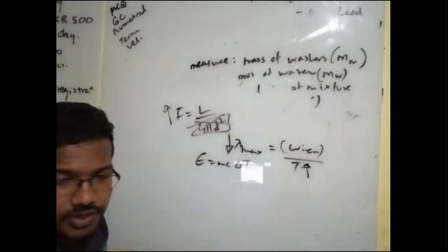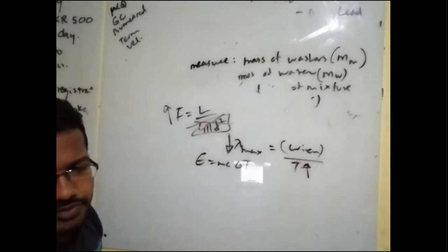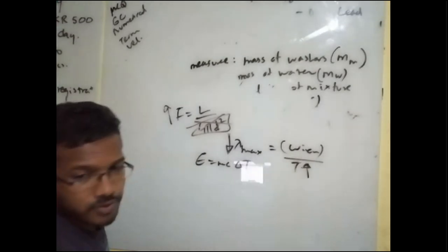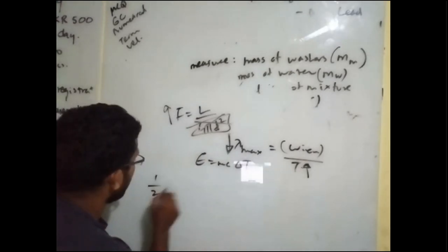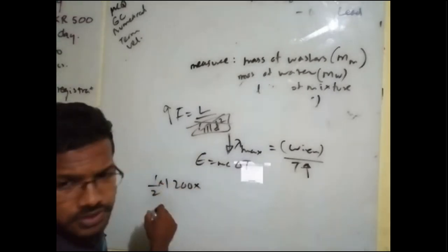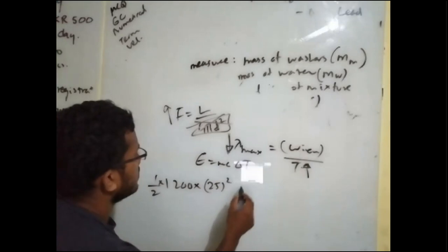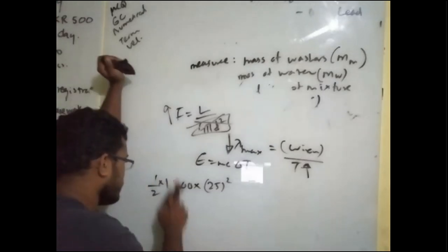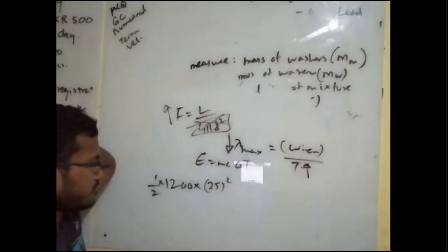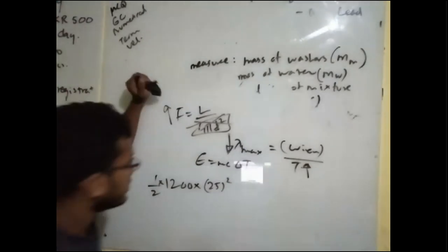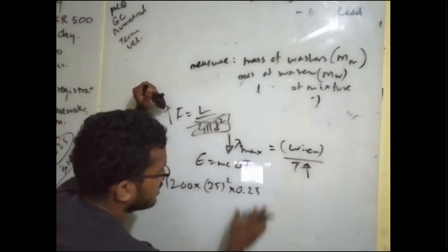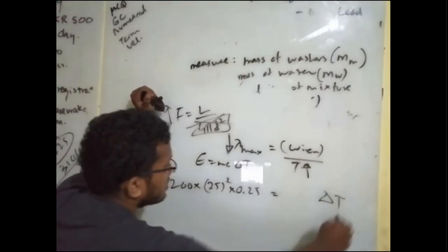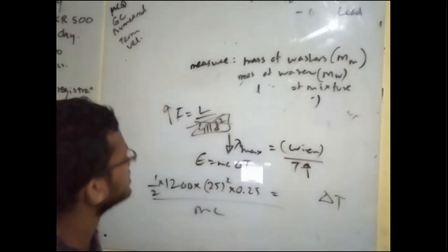I think they say a car of mass 1200 kg, traveling at speed 25 m/s minus 1. Oh, so the kinetic energy is converted to thermal energy. Read the question properly. Tell me a formula. Half mass velocity square. Am I done on the energy side? No, you're not, because it's 25% of the kinetic energy. So I'll multiply this by 0.25, or 25 over 100. Then only we put it in, and we are looking at the increase in temperature, so very easy. We won't waste more time on this.